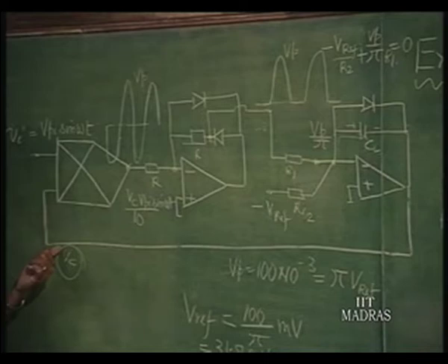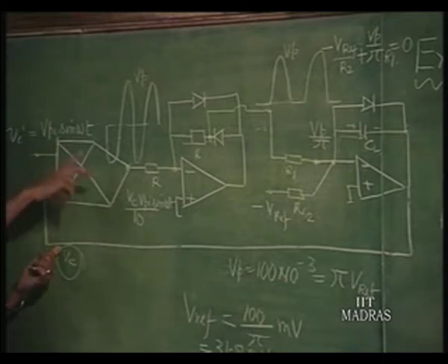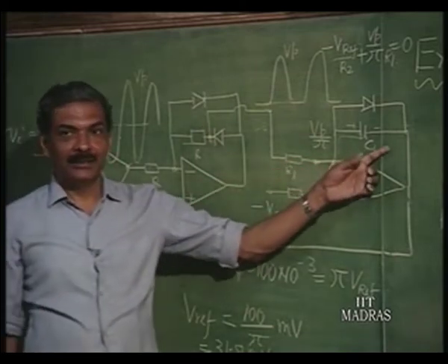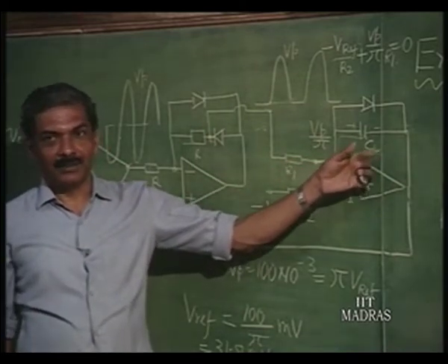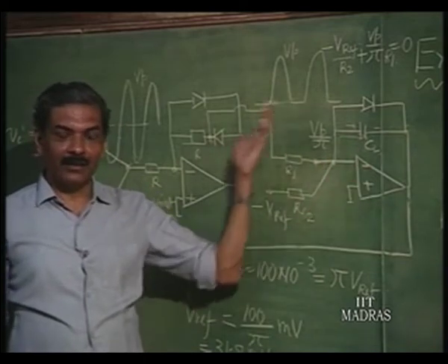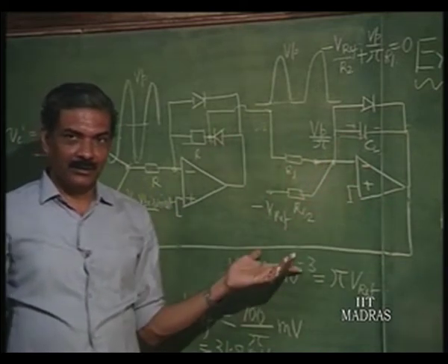So, instead of getting AGC, you will get an amplitude modulated output, because there is a carrier here, and that amplitude modulation frequency corresponds to the natural frequency of the system. If you find that, then you must change the value to a higher value capacitor. This is another important point in the design of such systems.